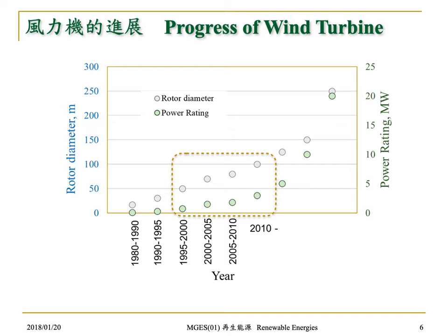Because if we install larger wind turbines, the installation cost per megawatt is much lower. But if you want to install a larger wind turbine, the materials, design, and structure usually have to be more engineered, because with a larger blade, for instance, the centrifugal force will be enough to tear the blade apart, and the magnetic strength also has to be considered.